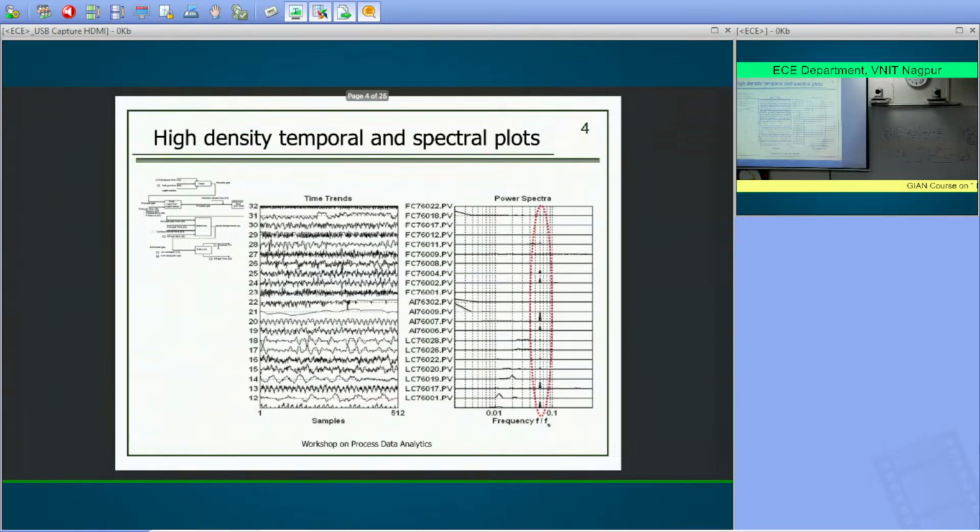Typically, in a refinery, you have multiple processes that are interconnected, right? You have upstream processes, downstream processes. If there are oscillations in an upstream process, those oscillations tend to propagate through the downstream processes as well. And that's what we're seeing. Now, just by looking at this graph, you can't tell where the problem is, where the oscillations originated.